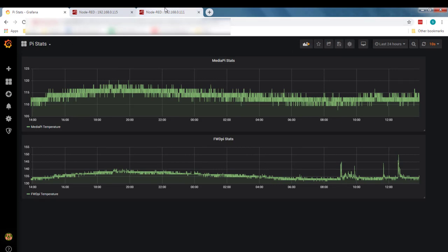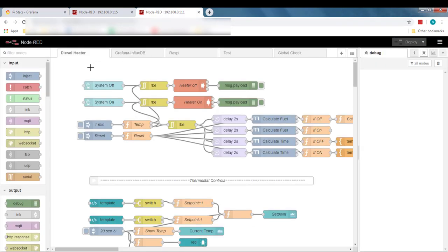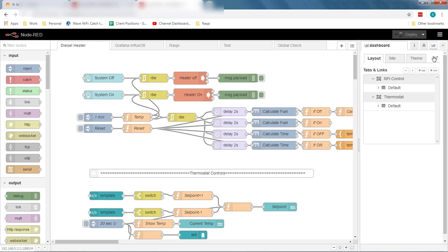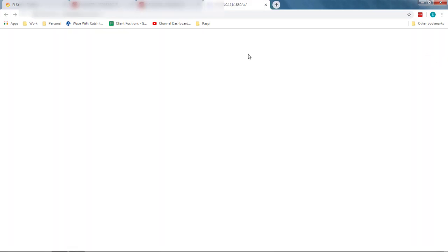I have two of the knockoff Webasto diesel heaters, and they use an RF radio signal for their remote. So I've pulled off one of the pins, I think it's GPIO 17. You can use it to transmit radio signals. So I can show you on the Node-RED dashboard.